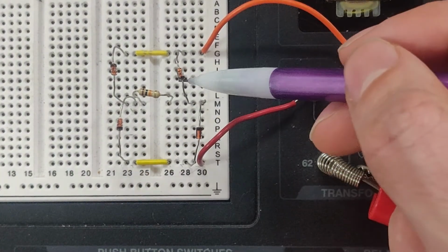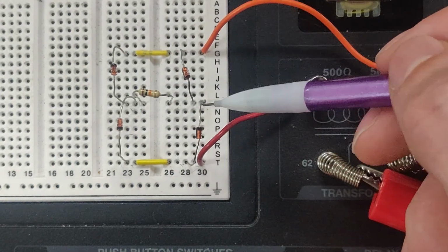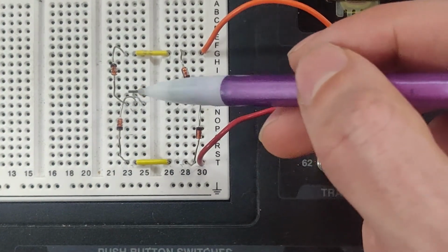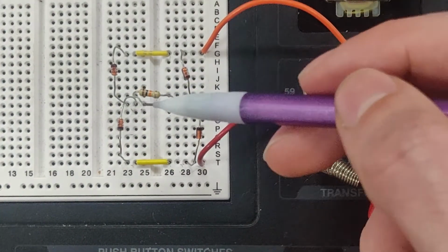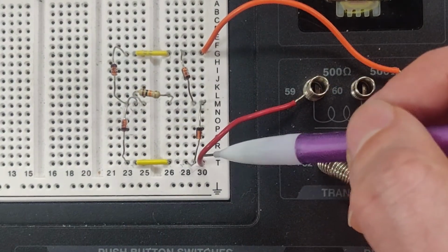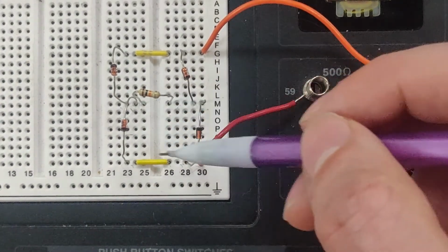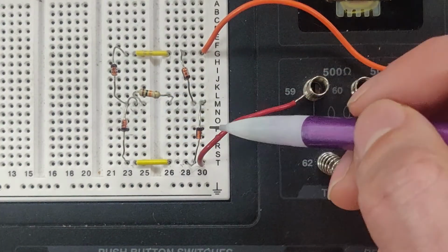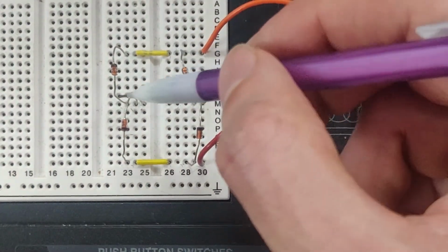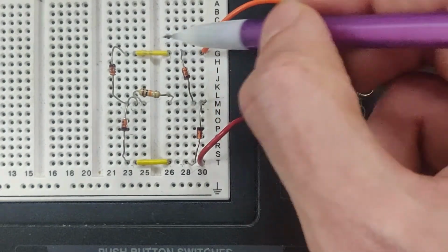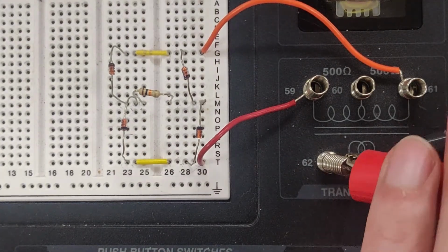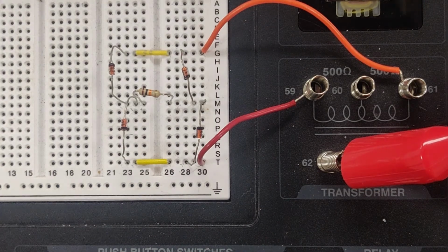So it can either go through this resistor or the diode, but relative to the current coming in, this is reverse bias, so it's going to go through the resistor. And then once again, we reach this junction, and the current coming in this way is also forward bias for both diodes. So if it goes down, it just will go right back up to this diode, just like how it was in the previous one. So it'll go up here, and because this is forward biased, it will continue on and complete the circuit. Okay, so that's roughly how current is flowing through the full bridge rectifier.